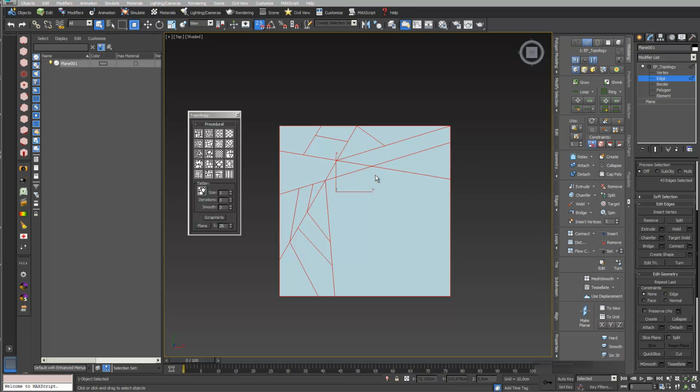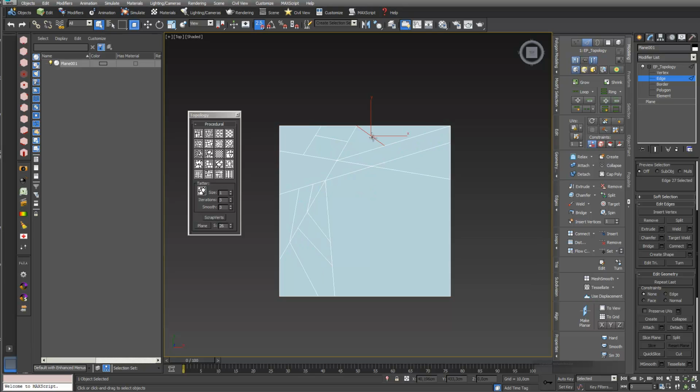And you can obviously also delete edges. For example, if I take this one and press the delete button, then you have a hole. I don't want to do this. So if you choose the backspace button, then you can delete it. I say Ctrl Z again, or you just go into remove, and that's the same thing. With this, you can just delete your topology.